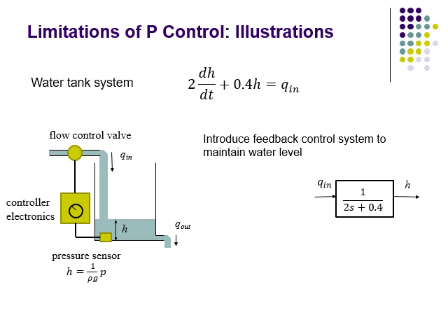The idea is that we use a sensor which is able to measure the height of fluid in the tank. For example, a pressure sensor would work. The signal from the sensor goes into the control box or the controller electronics, and then the controller electronics sends an actuation signal to vary the opening and closing of the valve so that we can set the flow rate through the valve. So we can set the value of Q in through the controller.